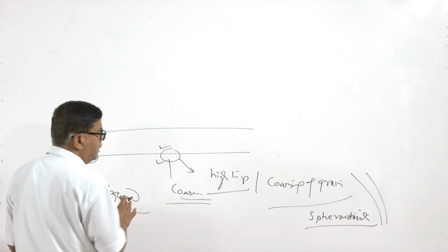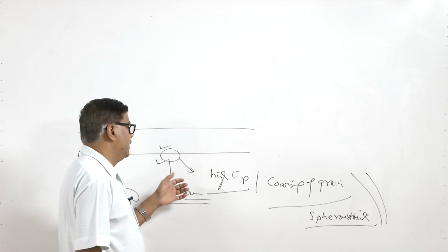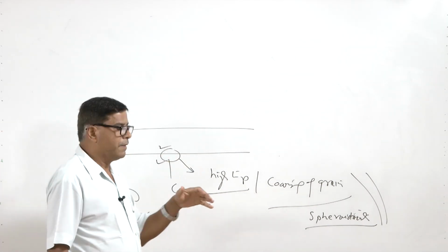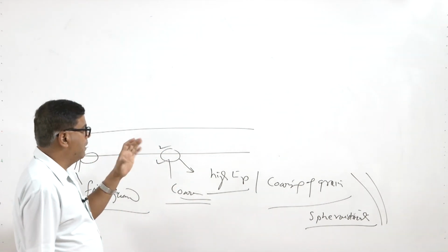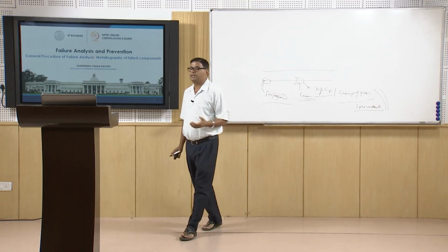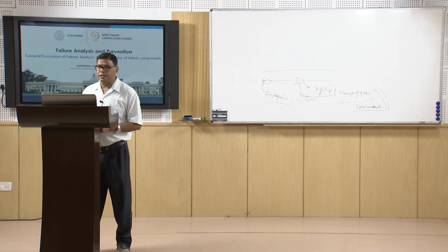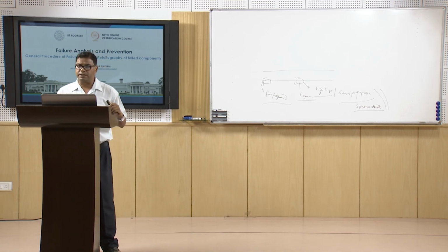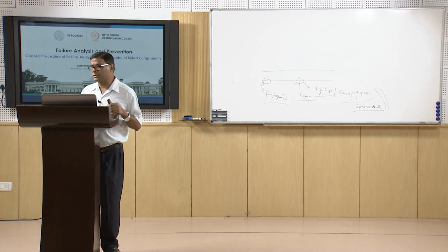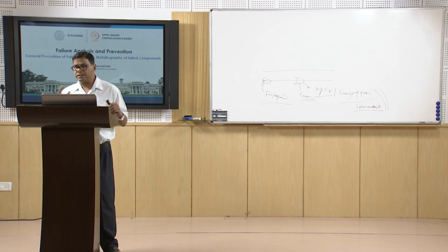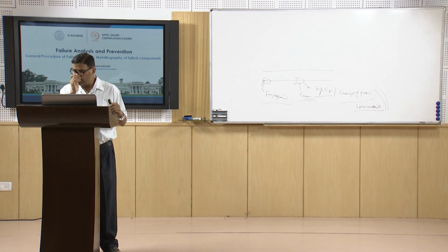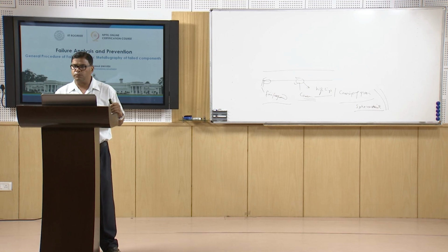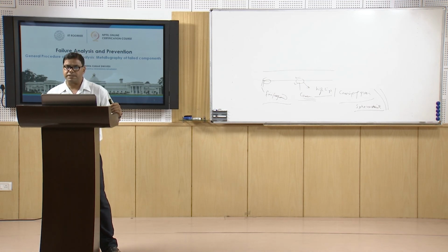So, excessive high temperature exposure can also be a possibility, accidental exposure to high temperature conditions, and it can be identified through the variation in the grain structure, which will be indicated through the coarsening of the grain. So, apart from carburizing in a carbon rich environment, a structural modification in terms of coarsening can occur at a high temperature. Similarly, the soundness of the components can also be identified through the presence of some voids or pores, if these are present in the steel.